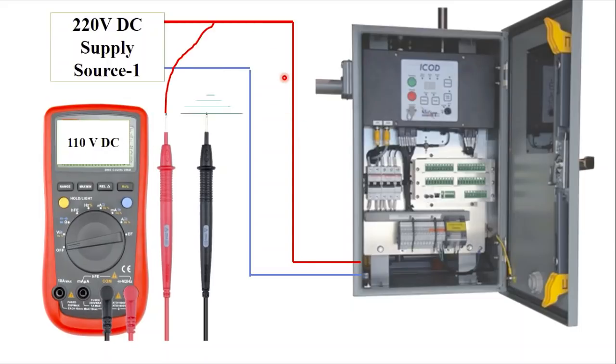Positive, right? Then you can say that positive DC earth fault is there. Then if you measure positive to the ground, how much will it show? This will show 0 volt DC. If this positive lead is completely grounded, then in that condition this multimeter will show 0 volt theoretically. Somewhere there will be a partial ground, it will not be completely ground. In that case it will not show complete 0 volt, it will show 5 volt, 10 volt positive, or it may show 55 volt positive. This may show anything practically if you measure. So it depends upon the wire condition, that how it touches the ground.